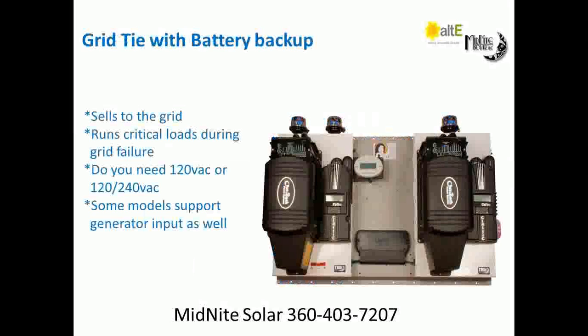Now, on battery banks, I didn't talk about it in off-grid, but typically when we size the battery bank for an off-grid scenario, we go for 2 to 3 days of redundancy, and we also look at not going below 50% state of charge. For normal, everyday use of a lead-acid, flooded battery, we typically don't like to go below 50%, just for longevity of the battery.